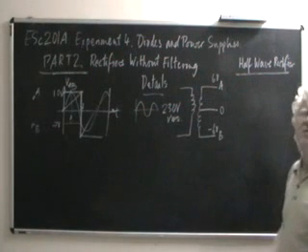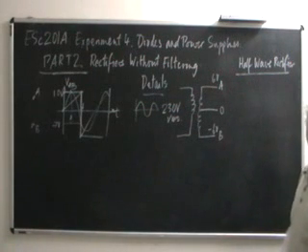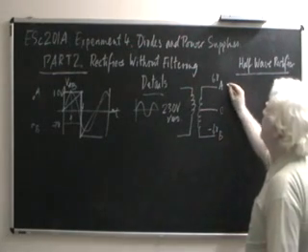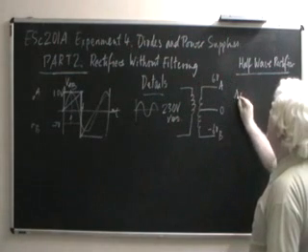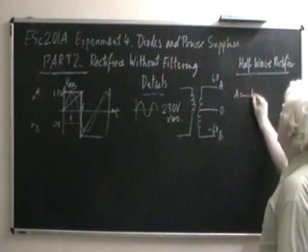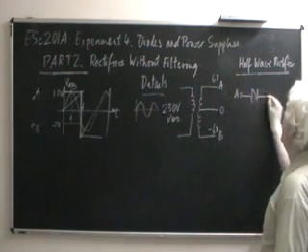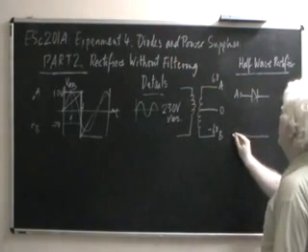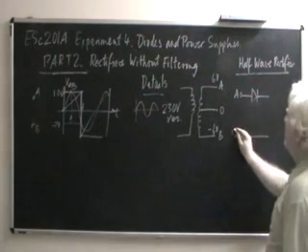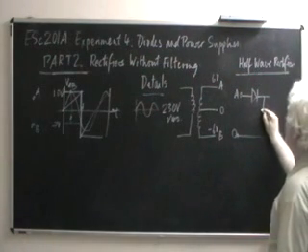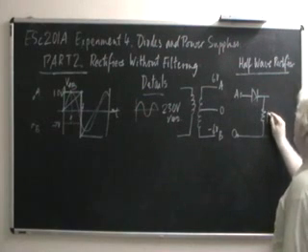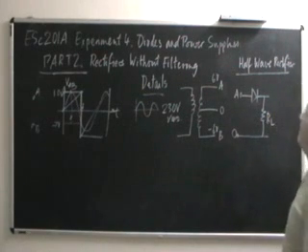The half-wave rectifier is a very simple circuit that uses just one diode, and that is connected to the point A. So you have this point A, you have a diode over here, and this is the point O, and here you have a resistor. This is the load, which we will call RL.